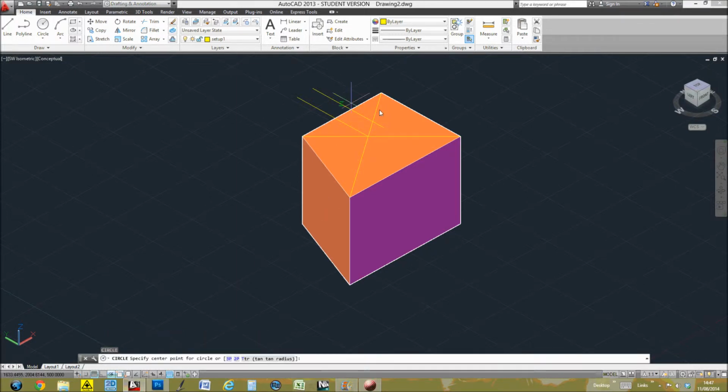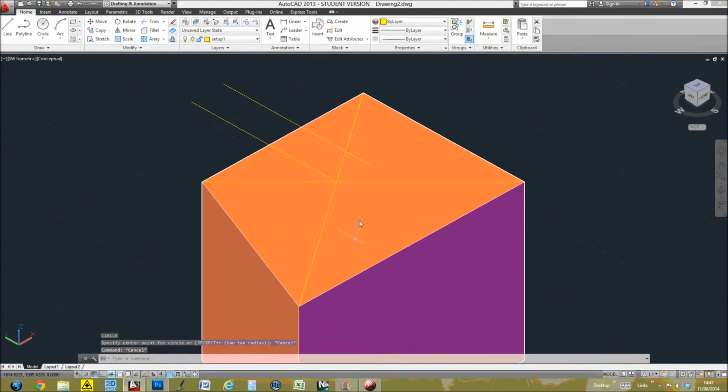So from this it's very easy for me to set up another drawing if I want. So in this case I'm going to set up a small square on top of here. I'm just going to do that by drawing a line from this point here, so I know it's flush there. I'm going to make this line 50 this way, because I want to set this about the middle of this point, so the square sits in the middle of this, and the square is going to be 100. So if I now bring this up 50, and then I just use my offset command again, but this time round, instead of setting the offset command to 100, I'm going to set the offset command to 50.